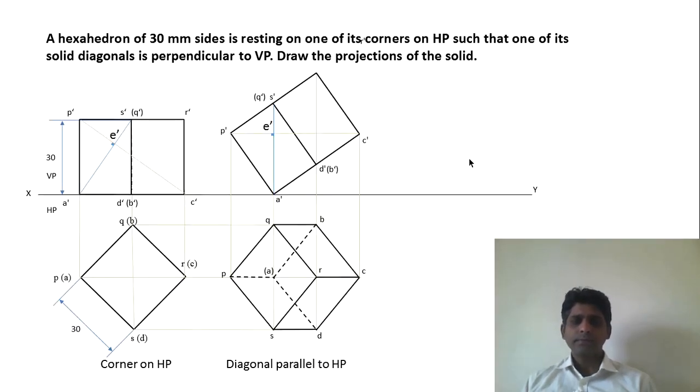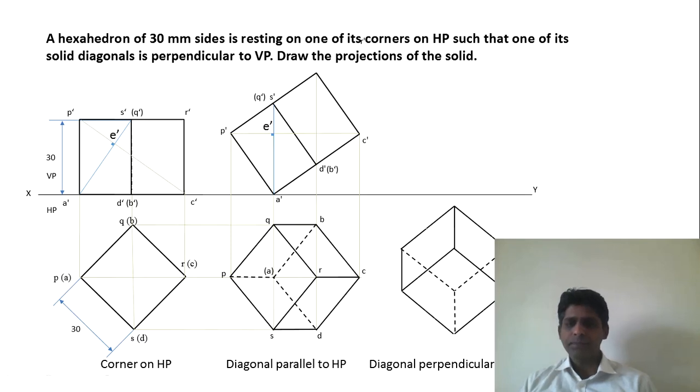So to do that, what we will do is we will draw one vertical line. I will just go through this and explain this. Yes. So we have to draw one perpendicular line. How to reconstruct this I am explaining. Draw one perpendicular line. Mark point C here on this perpendicular line. Then you can mark all the points. Measure CR, cut an arc on this particular line which is drawn. Then measure CA, cut another arc. Measure CP, cut another arc. So you will have points C, R, A and P on this straight line.